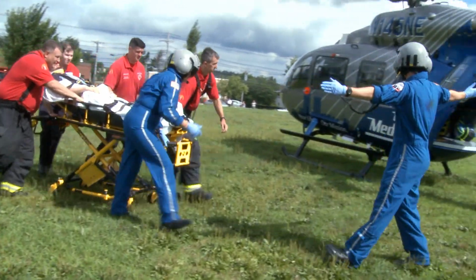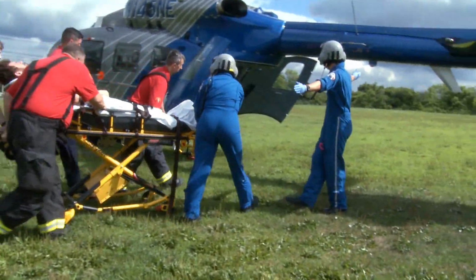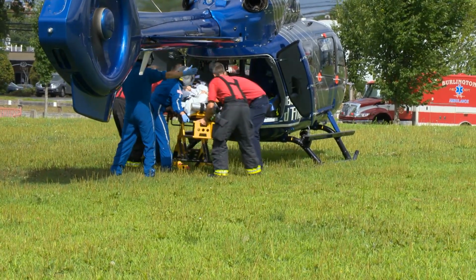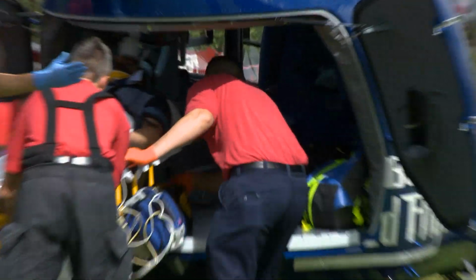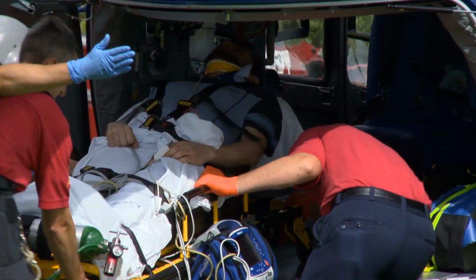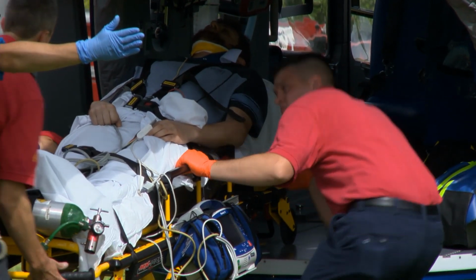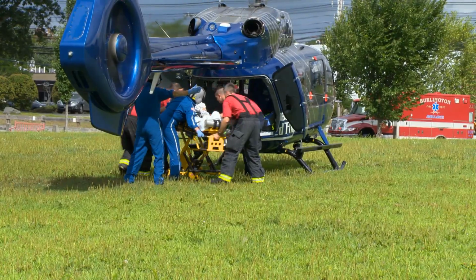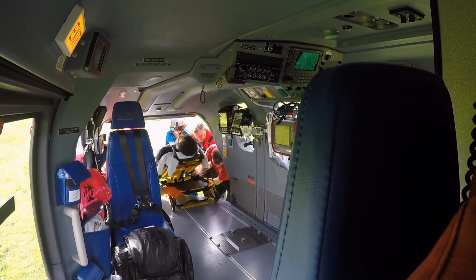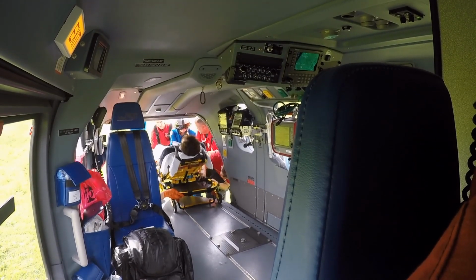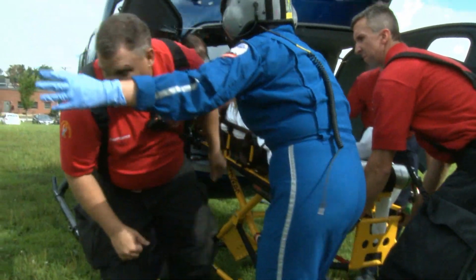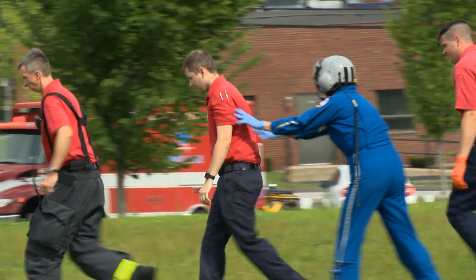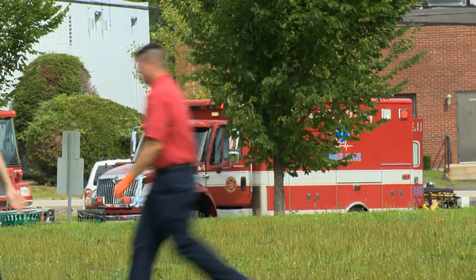The loading approach direction of this aircraft is 9 o'clock or 3 o'clock. The patient is moved toward the aircraft feet first and then turned prior to going under the main rotor blades and loaded into the aircraft head first. A crew member will guard the tail of the aircraft. Never move behind the tail guard. Once the patient is at the aircraft, a crew member will escort the fire department or EMS load team under the rotor disc and away from the aircraft in the same direction from which they entered.